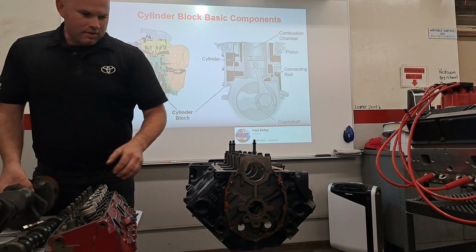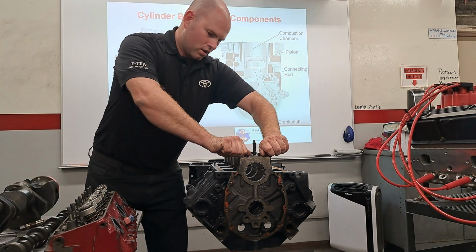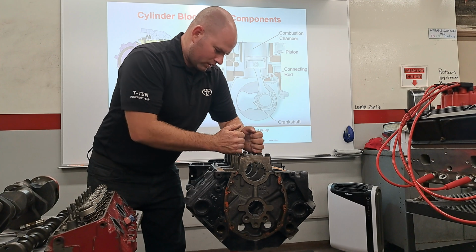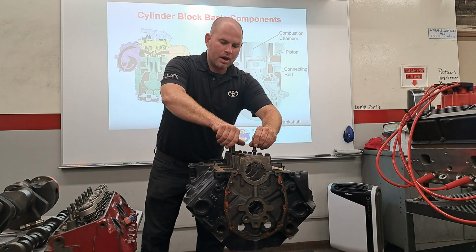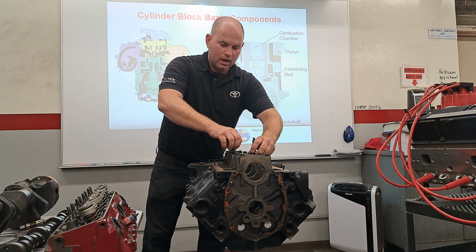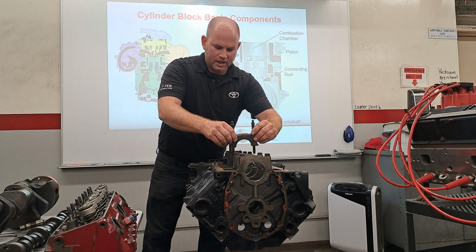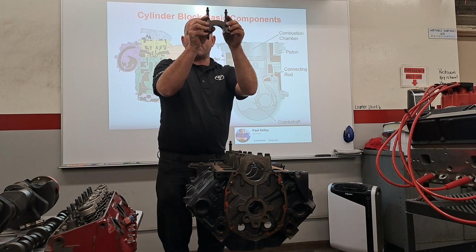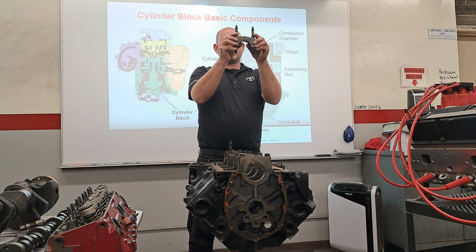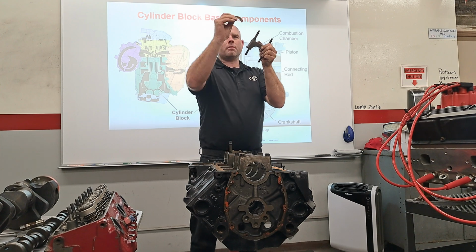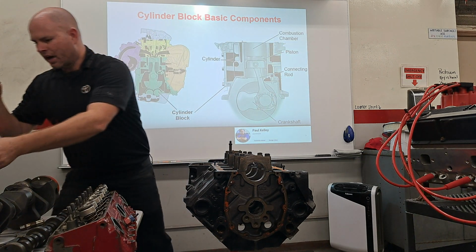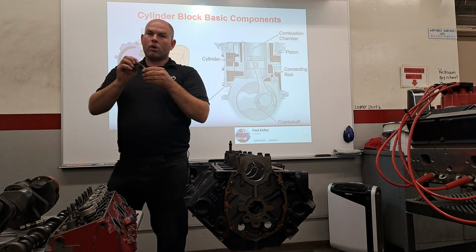At least I checked, one of these is loose, so I'm going to just pick this one. I'm going to pop one of these main bearings out, and then I want to discuss what that oversized means. So this is called the cap, by the way. This is a main cap. This right here is the bearing. So I'm going to just set this down. I'm going to set it down in order so I can put it exactly where it goes. This is the main bearing.